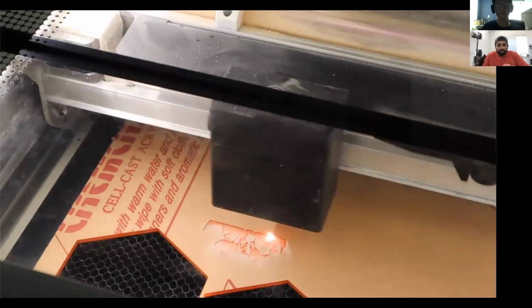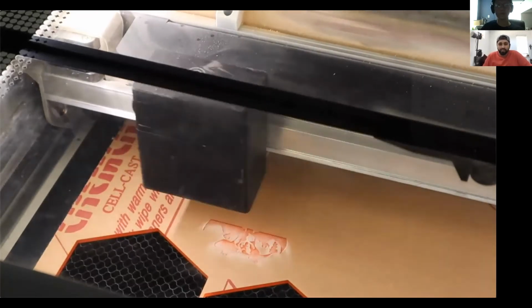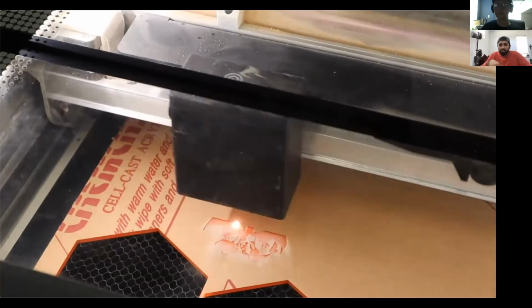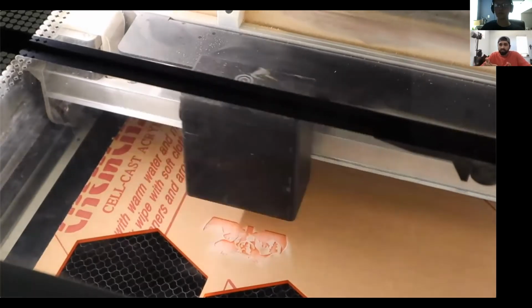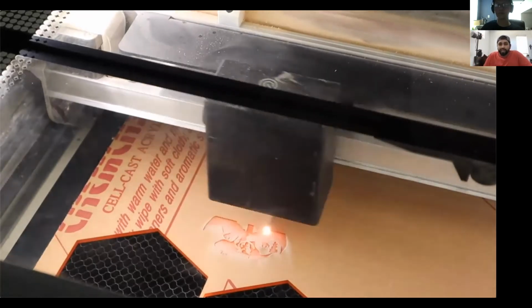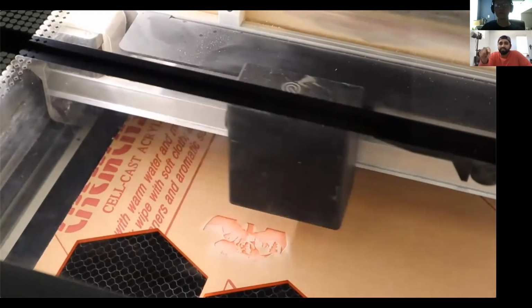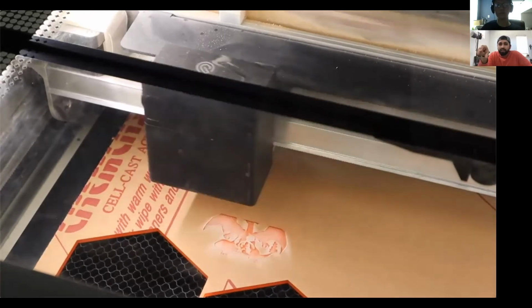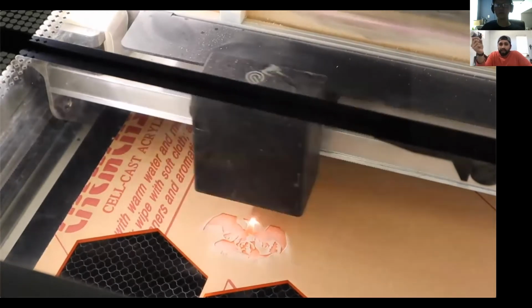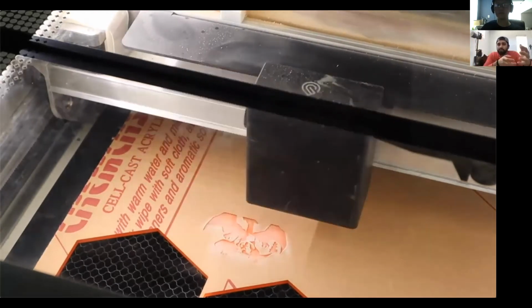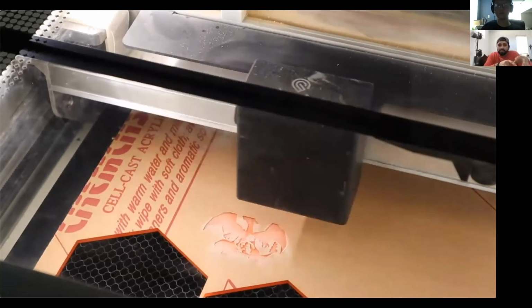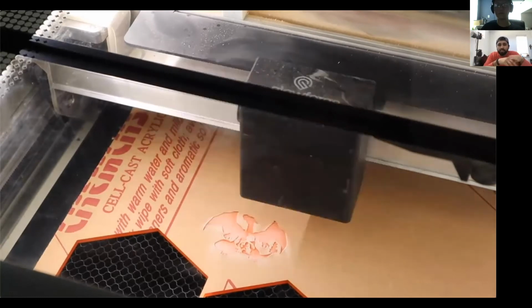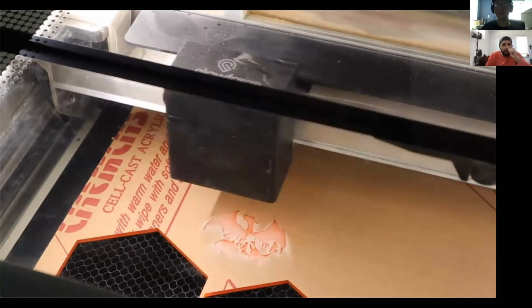Also, like I mentioned before, this is the engraving process. It does really quick, really shallow passes up the side of the entire image. You can change how many lines it does per inch of image. I think right now it's 200 per inch, but you can increase that if you have a really small part and you want higher resolution on your final laser cut, or you can also decrease that if you really don't care what it looks like and you're just trying to get a prototype done.